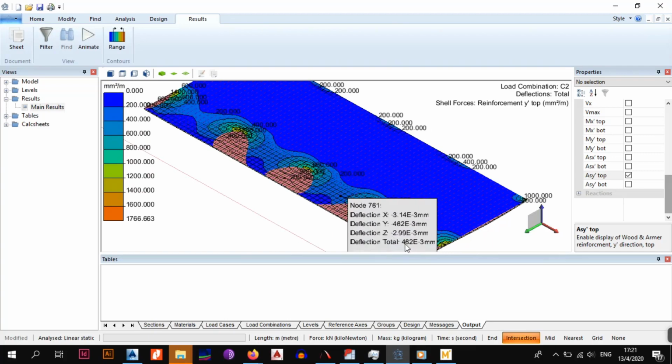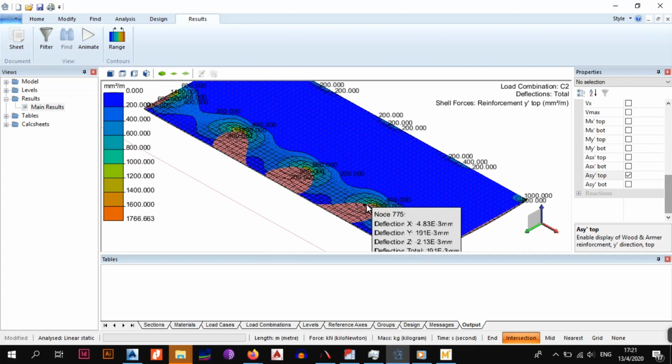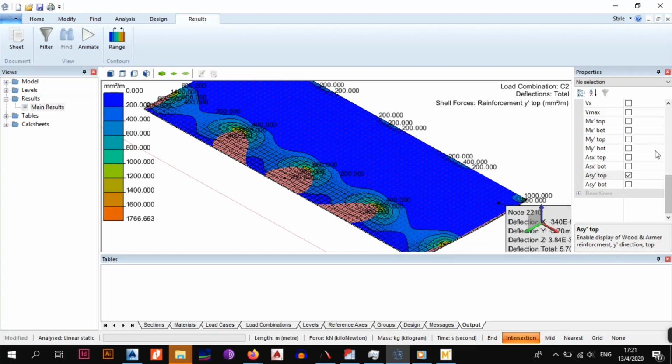And the reason why you have most of the load at the supports as well, the hogging moment, is because you have a wall on top and you have 5 kilonewtons, but then when you look at it, at the other side there is no load, so you have a wall and then you have the area load at this point. That is why your moments are also larger, because the load that is being experienced at that point is quite huge.